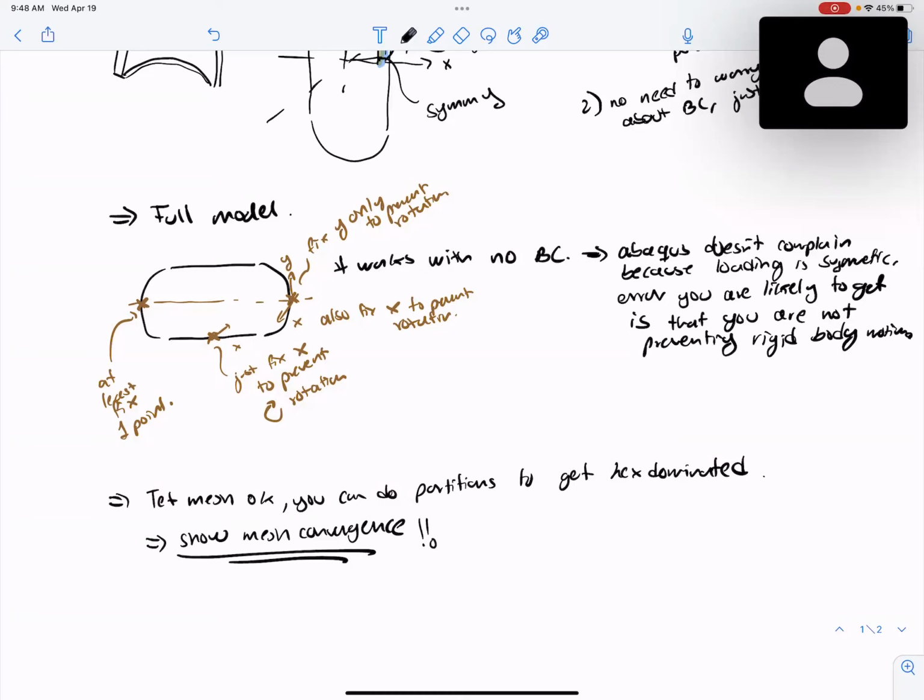That's it. Aside from that, this is a nice problem. There's not much bending. It is mostly in plane. Stretching is a little bit of bending, but it's not bad. So I think even the reduced integration elements probably do okay. I don't think they show any unstable mode.